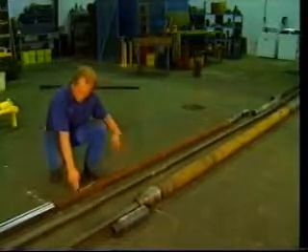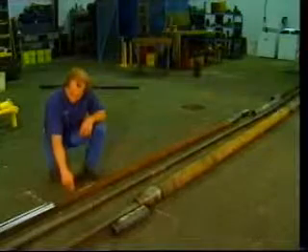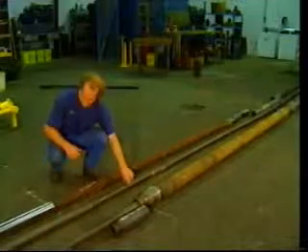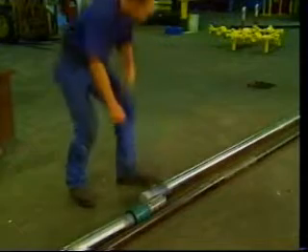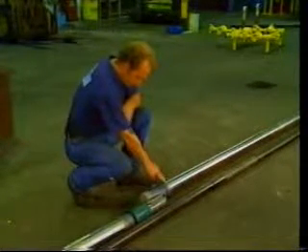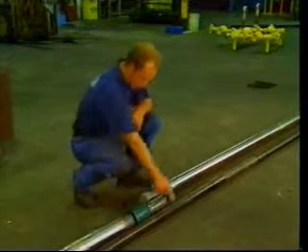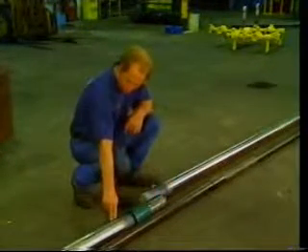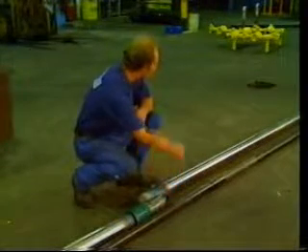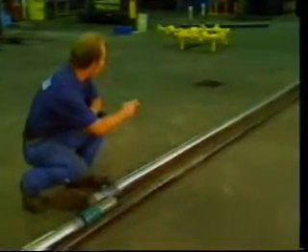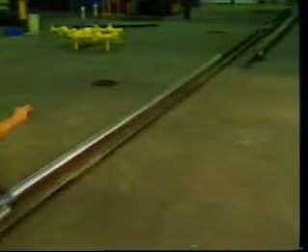A crossover sub and shear-out safety joint are attached to the lower extension. Below the safety joint, a length of blank pipe is run that is usually 3 times the length of the screen. Centralizers are necessary to facilitate proper gravel placement in the screen casing annulus. The wash pipe runs inside the blank pipe and gravel pack screen. At the bottom of the screen are the lower centralizers, the O-ring sub, and the telltale screen. The wash pipe extends into the telltale screen. The wash pipe and the gravel pack assembly will be pulled from the wellbore following the gravel pack operation.